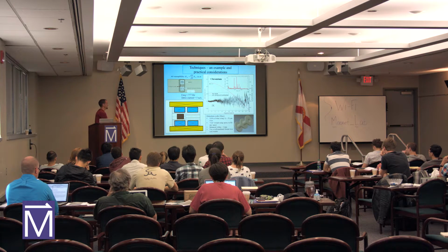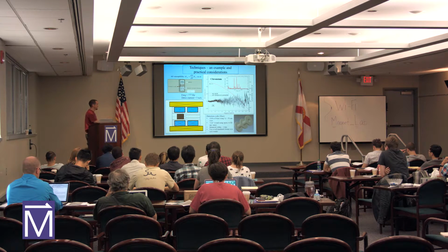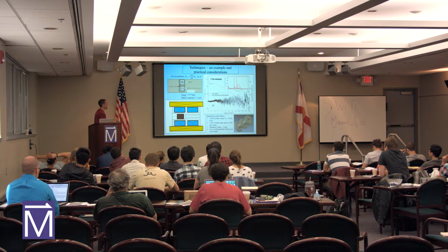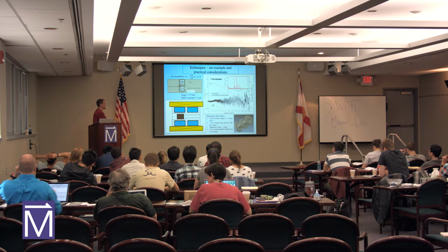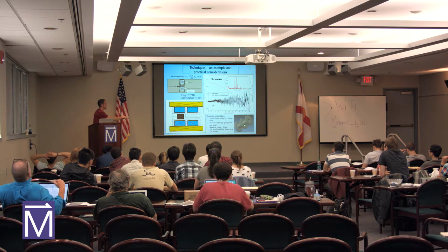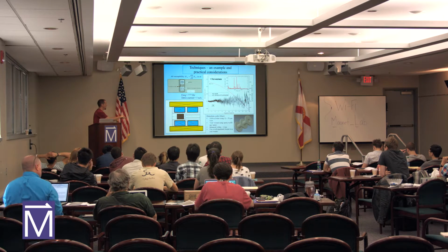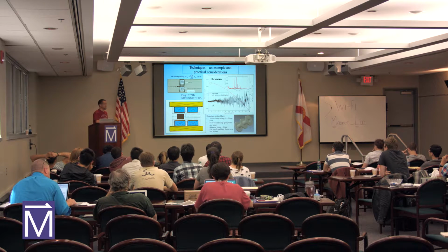That creates noise. When you wind all the windings on there, you take your former with the coils in place, and you stick them into the excitation coil, and you make some small AC field with the drive coil, the excitation coil. And when that happens, you see how much of a signal you get in the detection coils. You pull it back out, and you adjust the amount of windings around either end on the former until when you finally test it, you see almost 0 signal.